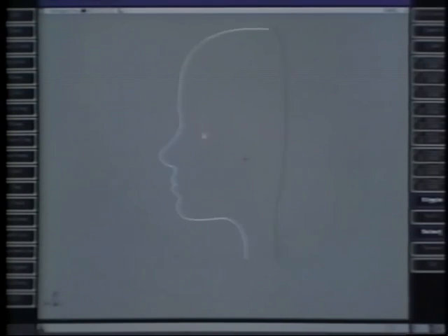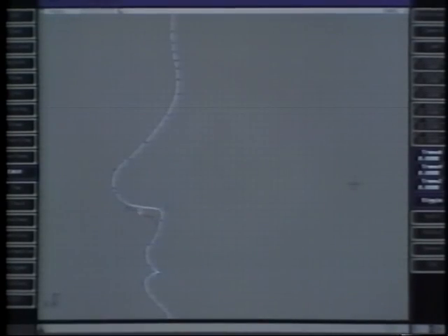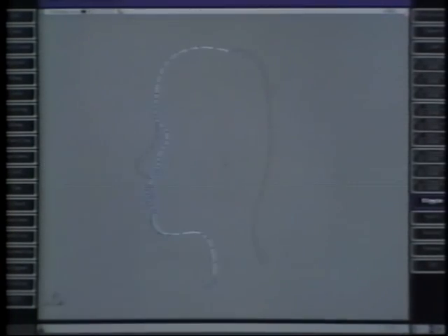The curve next to the profile will not have the nose sticking out as far, so we can make a copy of the profile and move points, but not delete them, to get rid of the nose and start into some eye sockets. The mouth will be tapering off by now too, and we can rotate our modified curve a little ways around the central axis.